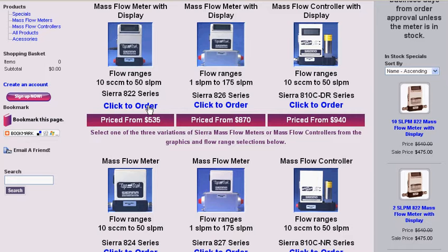These are also part of the challenge of measuring flow, is calibrating them. All of these are calibrated with primary standards, not secondary standards. Primary standards, the uncertainty level or accuracy is 0.2%, and the 4-to-1 rule is 4 times 0.2 is 0.8. If you use this meter as a transfer standard, a 0.8% device, to calibrate another, that's 3.2%. Most of our competitors calibrate everything with transfer standards. Therefore, they cannot say that the uncertainty level or the accuracy is 1%. It's 3.2. 8 times 0.4 is 3.2.